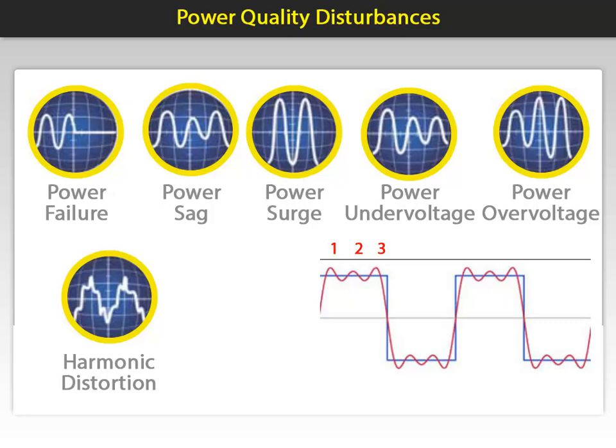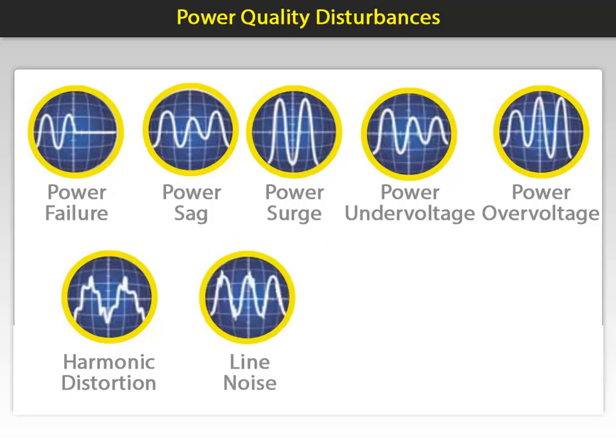Another nuisance that causes issues for electronic equipment and disrupts data transmission is line noise. This refers to unwanted electrical disturbances on the power line, which significantly degrades power quality by introducing random variations in voltage and waveform. Essentially, it acts like static on a radio signal, corrupting the clean power supply needed for proper functionality. This causes havoc on communication lines in a facility such as Wi-Fi.